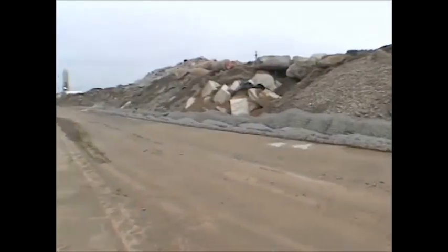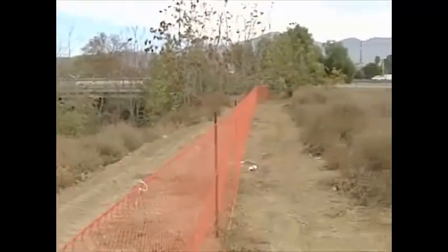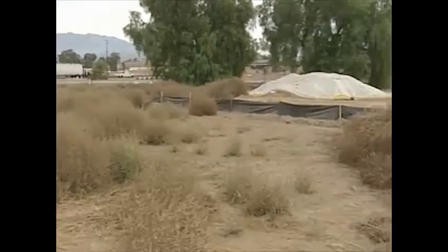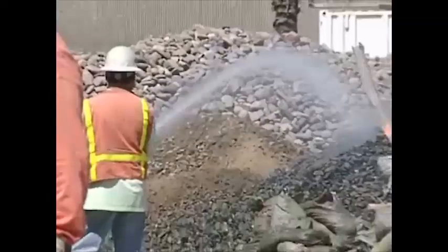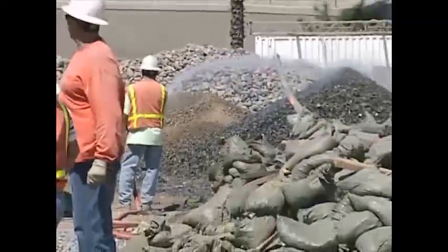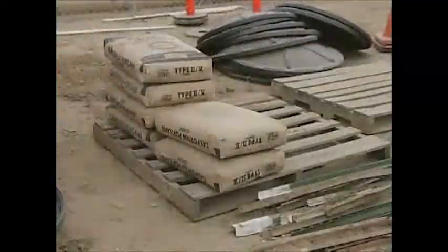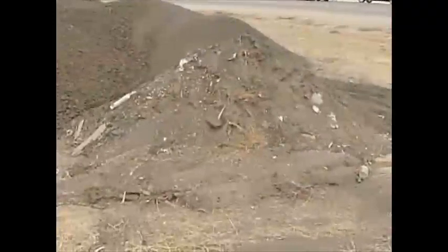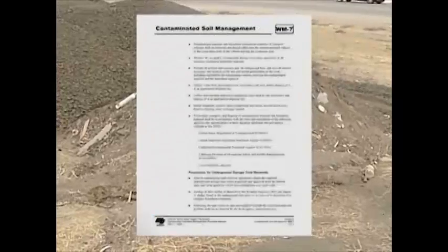Protection of stockpiles is a year-round requirement. Locate stockpiles a minimum of 50 feet from concentrated flows of stormwater, drainage courses, and inlets. Implement wind erosion control practices as appropriate on all stockpiled material. Place all bagged materials on pallets and cover with plastic. Manage all stockpiles of contaminated soil in accordance with the Contaminated Soil Management BMP.